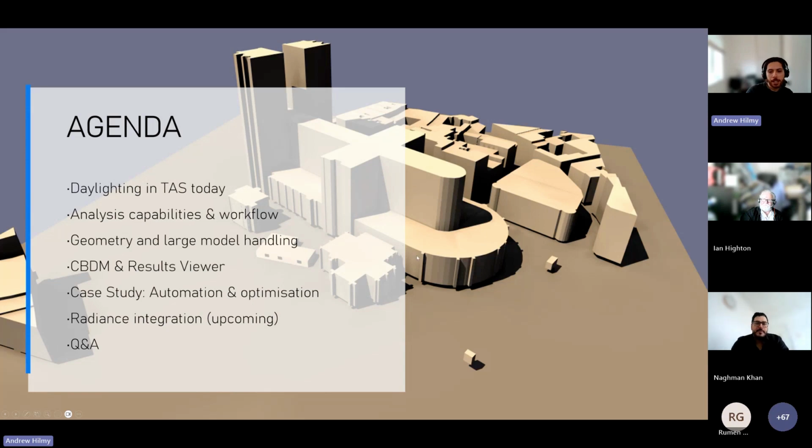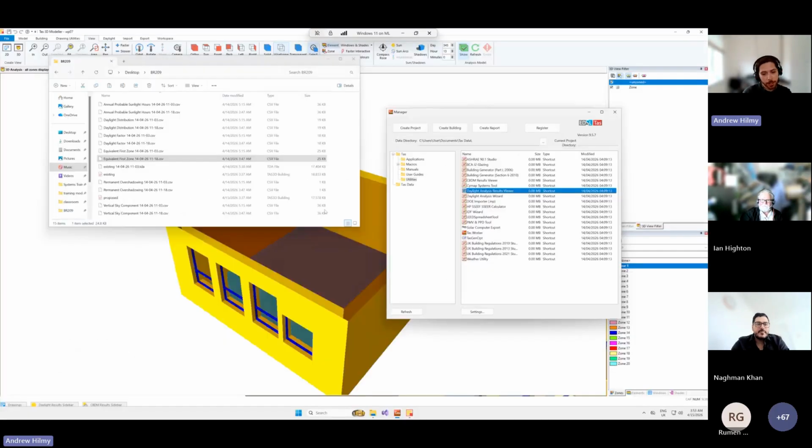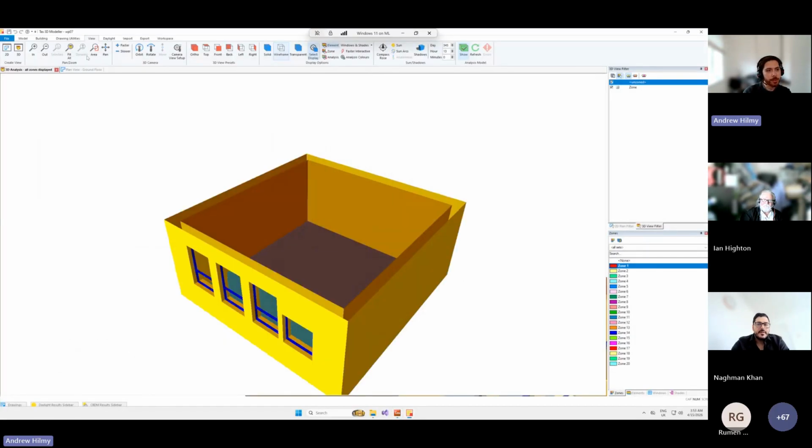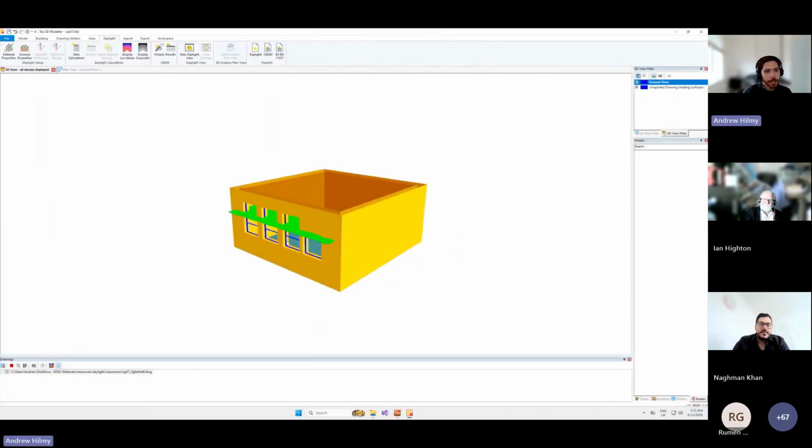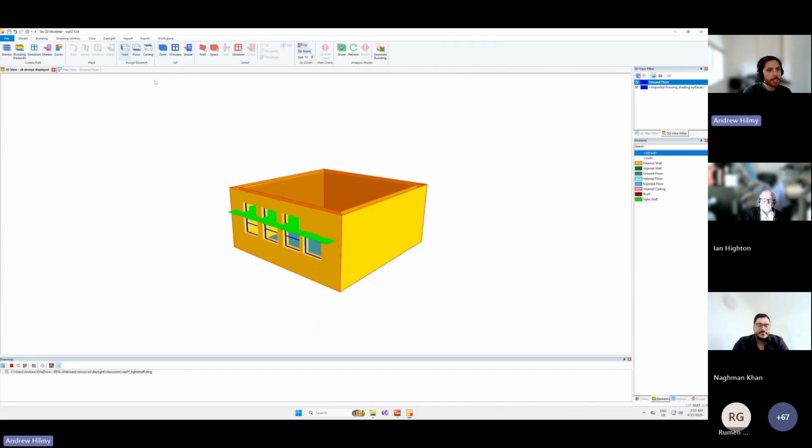But you can change things like the reflectances and transmission values of those imported surfaces. And that will be based on the layers, is that right? It doesn't even have to be based on layers, but yes, once they are imported, that's the easiest way to do it. But when you're in the 3D view, you can assign a different building element to that surface if you want to. So you could have 3 or 4 different surfaces in the same layer in the imported file, and then you could use the set element tool to change.